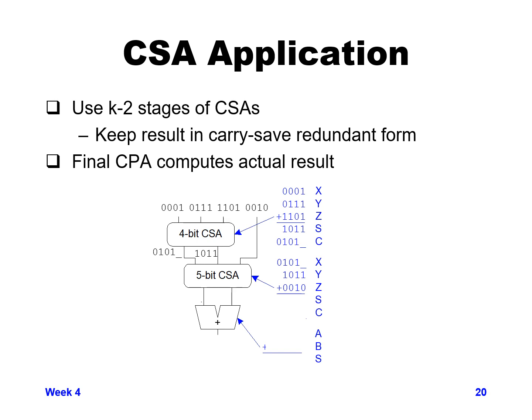So from that 4-bit CSA, we get 2 outputs. All of the C 4 through 1 and S, our carry and our sum, are both coming out of the CSA bits. Since our carries are coming out as 4:1 and our sums are coming out as 3:0, the carry is actually shifted relative to the sum.